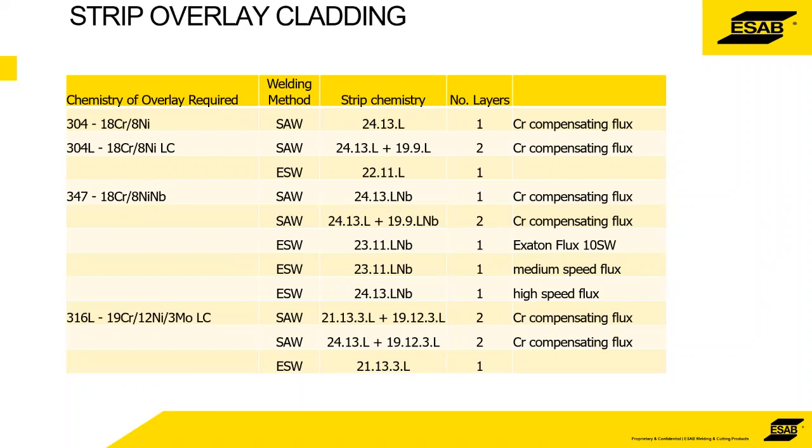I've had instances the opposite way where the specification was a maximum height of, I think it was 3mm, and again that's just as difficult. Obviously you've got dilution in there, and to achieve the chemistry on such a thin overlay makes a big difference, and it's tricky. It can be done, but it's tricky. But I absolutely agree with you there, Paolo, about 7mm. I think that's pushing it. Can be done, but with care.